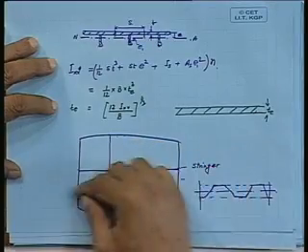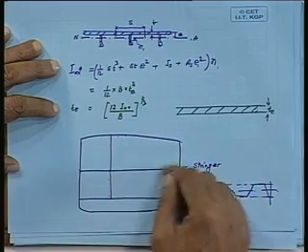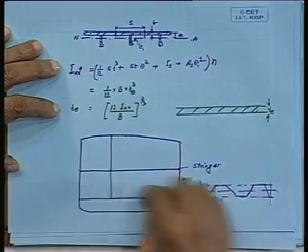And moreover, if you give it on the horizontal side, the lower you go, the hydrostatic pressure will be more. So at the lower end you may require a heavier cross section. For example, if you want to stiffen the bulkhead plate with horizontal stiffeners, when flooding takes place it will be triangular loading. So what is the pressure coming at the bottom stiffener?